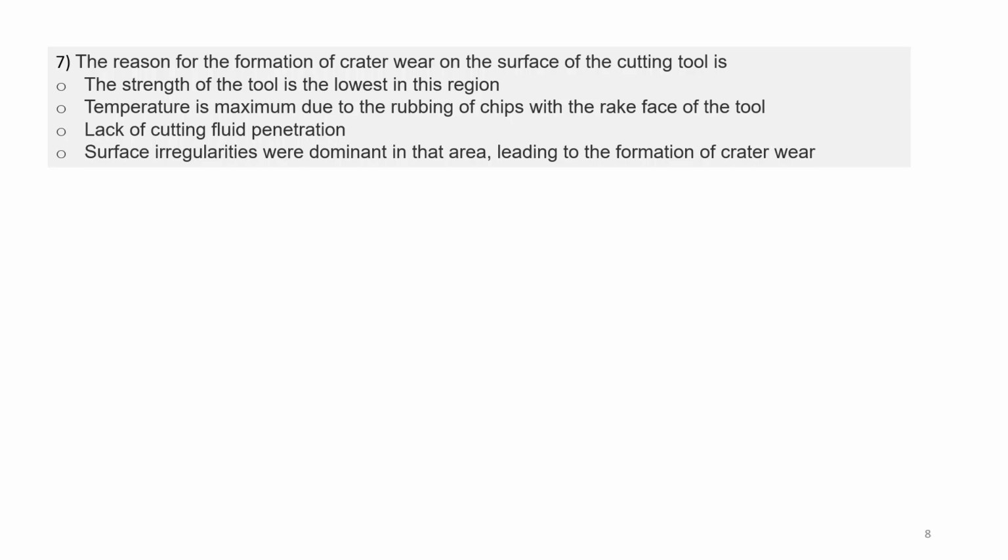Next question: the reason for the formation of crater wear on the surface of the cutting tool is. Your options are: the strength of the tool is the lowest in this region, or temperature is maximum due to the rubbing of chips with the rake face of the tool, or lack of cutting fluid penetration, or surface irregularities were dominant in that area. So the answer will be the second one.